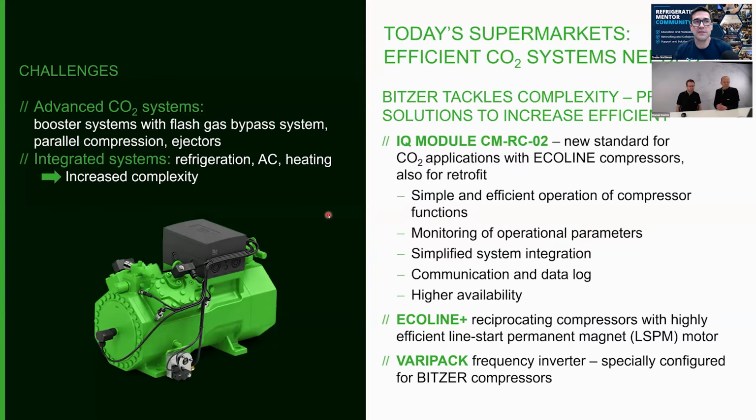Yeah. And this is a question I've got over the years all the time. Well, when should I use a frequency inverter, or when should I use mechanical capacity control? And Tobias just said it there. If you need a higher turn down rate, that's when you're probably going to want to go with the Varistep versus a frequency inverter. Is that correct? Yeah, that's correct. We have some nice pictures later. Personally, I would prefer the frequency inverter, but I'll show you on the next slides.